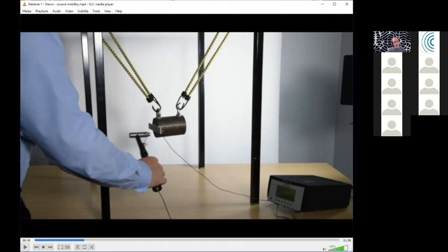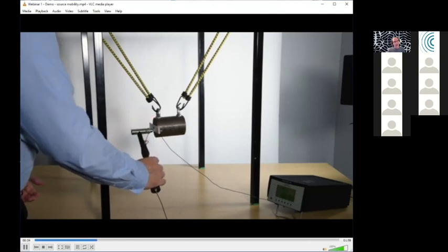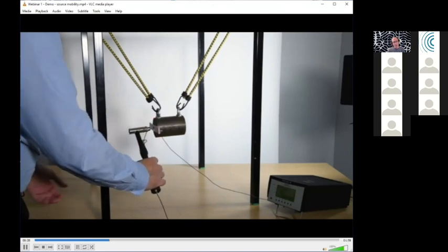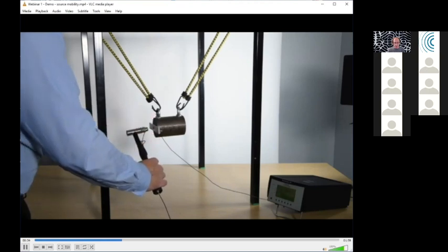And this time we've got a thin strip of metal that's bolted in the center. The accelerometer is fixed on that outer edge as if it was a fixing point on the edge of the compact pump. And then Gary is going to hit just opposite the fixing point of that accelerometer there. So as before, we take several averages, and because it's rocking a lot now, after each measurement it has to be steadied to make sure it's stationary before we do the next one.